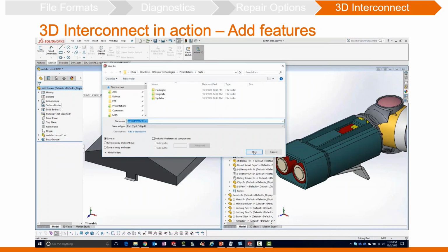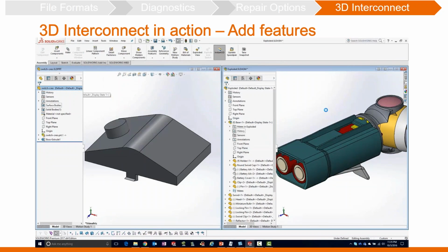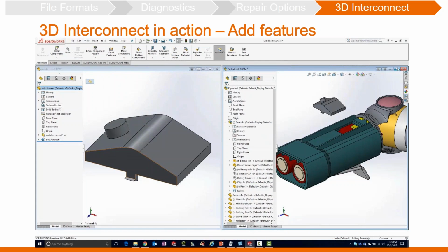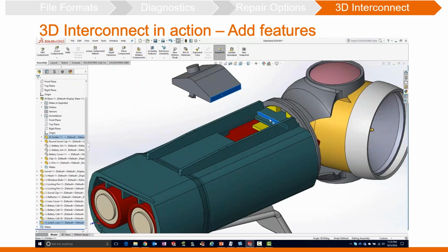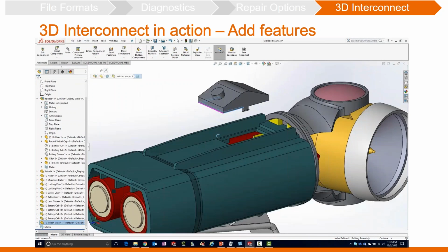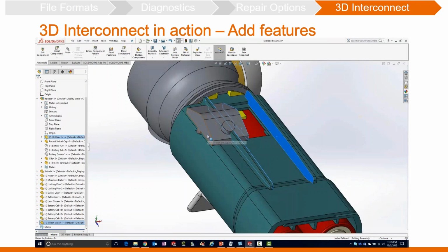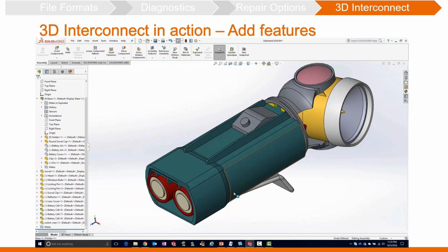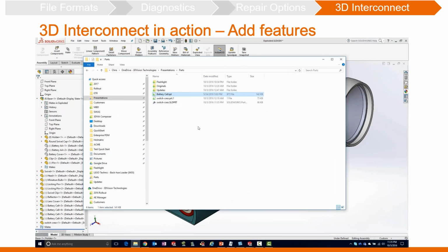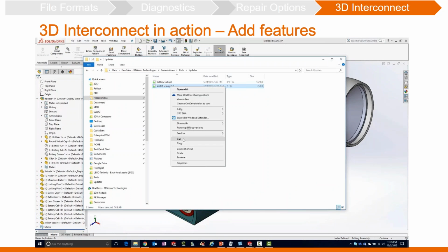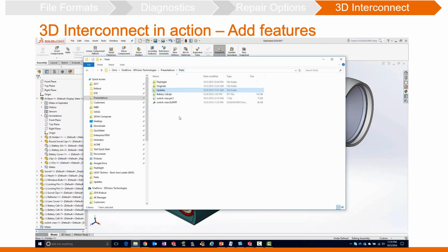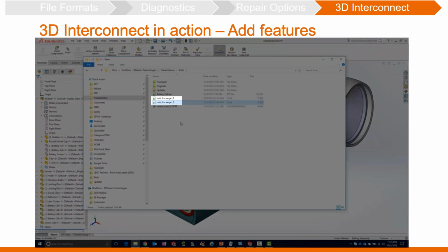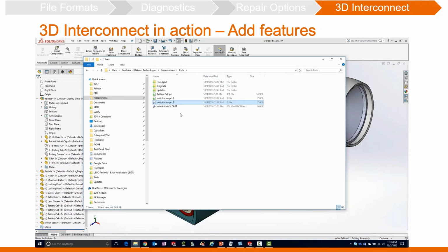So we haven't done any file import, haven't done any import diagnostics yet. We have very good geometry to work with. It's been almost exactly like working with a native SOLIDWORKS file, which is great. Sped up the video here a little bit to show how we're going to assemble that, and then we're going to walk through an update. So somebody has updated the Creo part. So you see the .2 extension. We're going to paste that into our window here and show that on the screen.